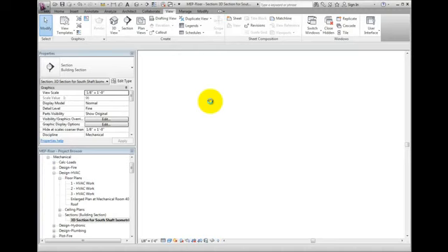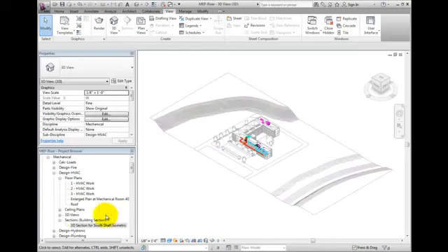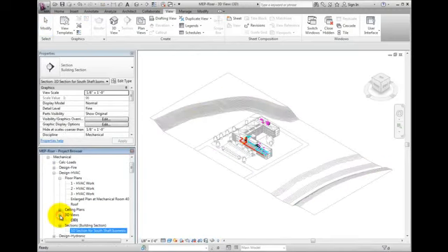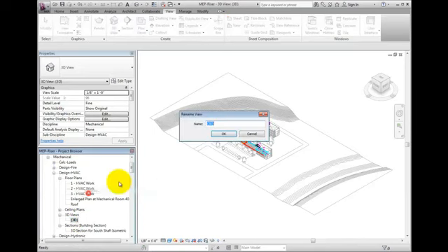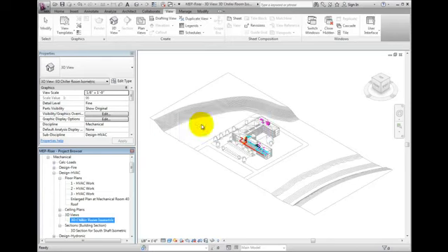Something strange happened. Revit just opened a view I already had created. This is because Revit will not create a new 3D view if you already have one called 3D. I will rename that one in my project browser the 3D Chiller Room Isometric. I will now create the 3D view, select the default 3D view from the panel.